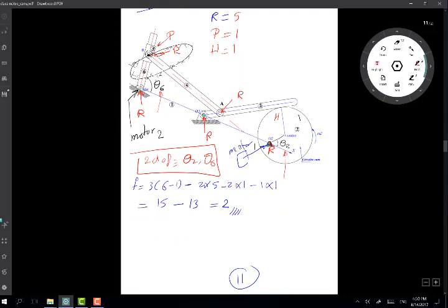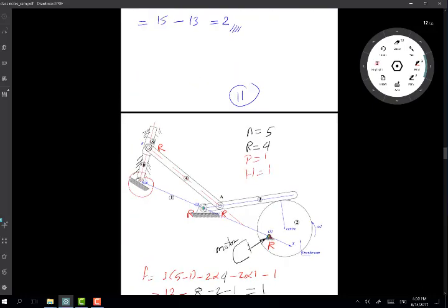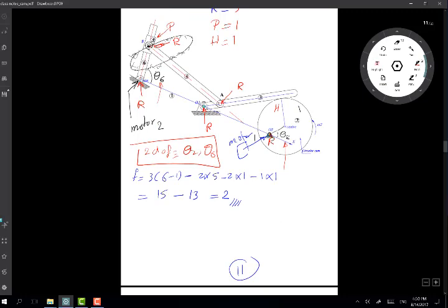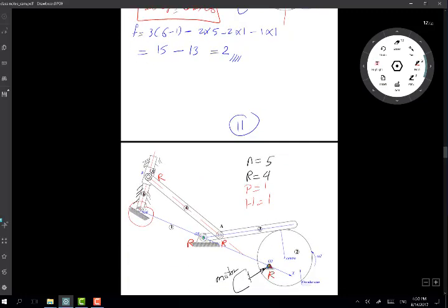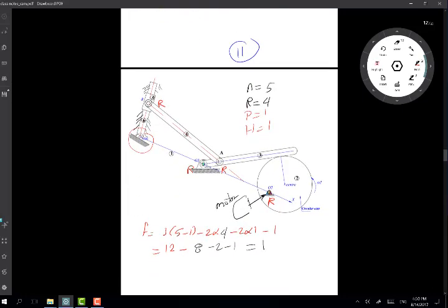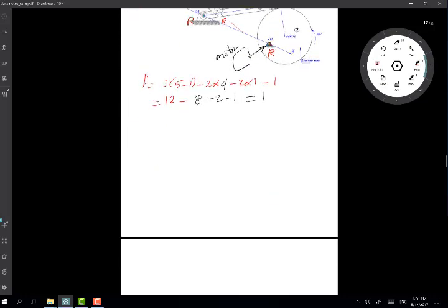Even in the case when I fix link number 6, imagine you decided to lock the motor which provides theta 6 at a specific value. Then you get a single degree of freedom, because you decided this motor is going to have 0 velocity, and so link number 6 becomes stationary, like a ground. All right, so let's look at some other interesting examples.